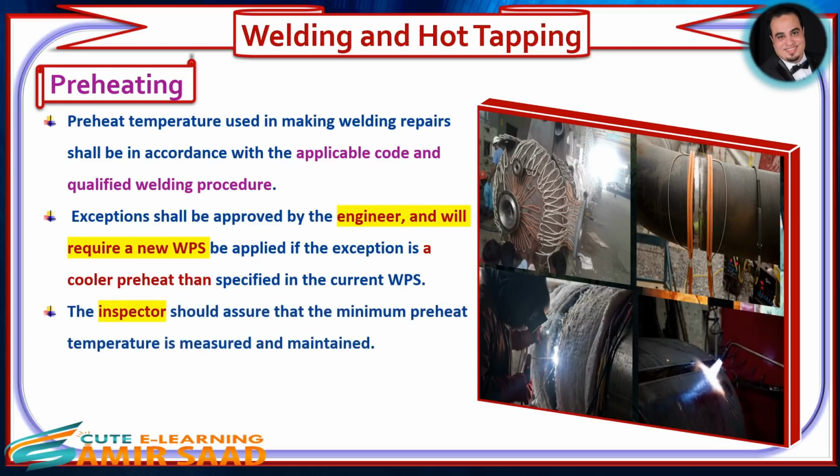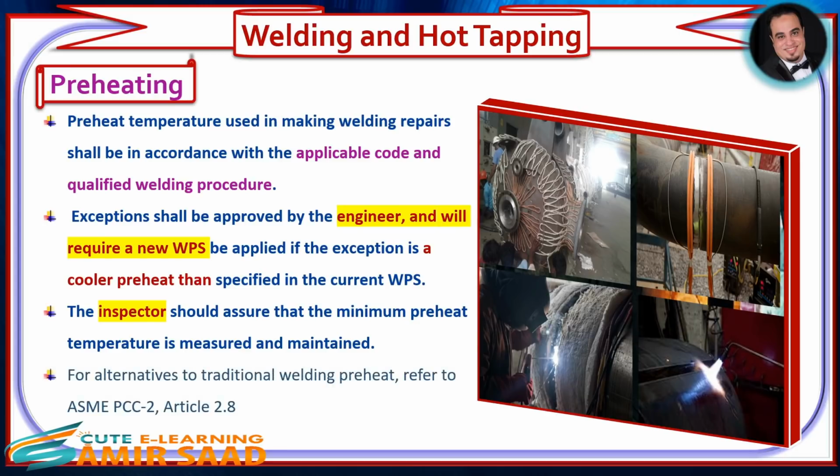The inspector should assure that the minimum preheat temperature is measured and maintained. For alternatives to traditional welding preheat, refer to ASME PCC-2, Article 2.8.